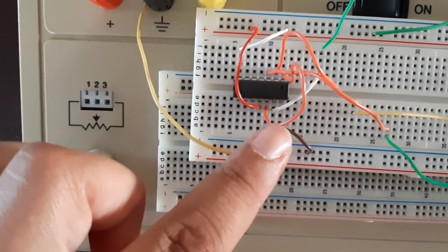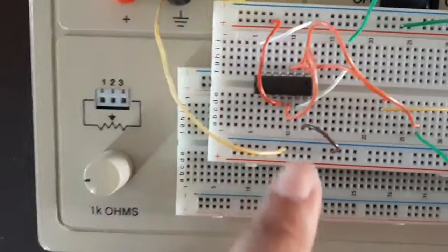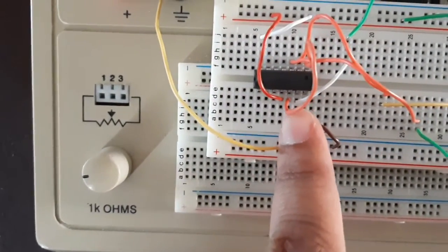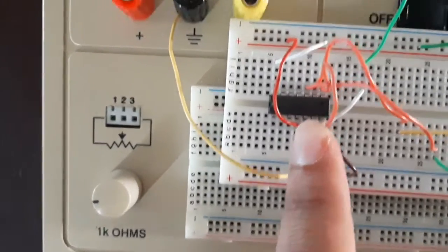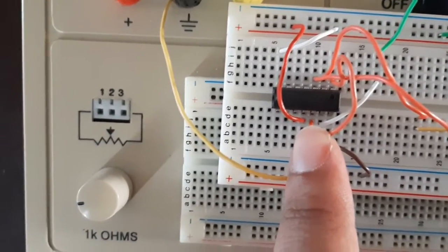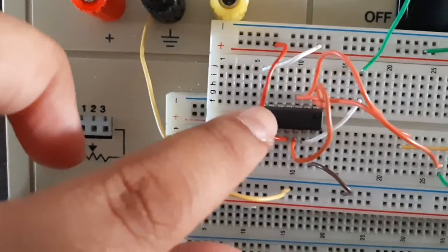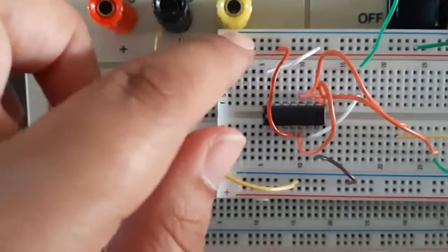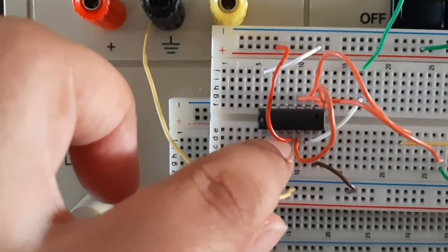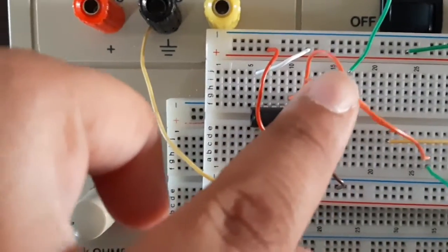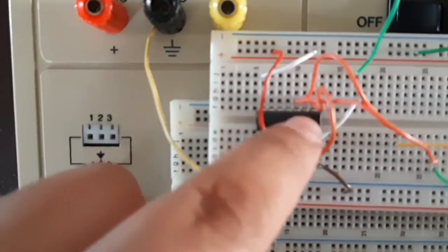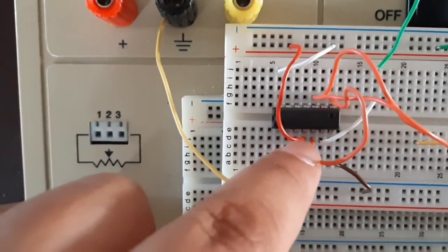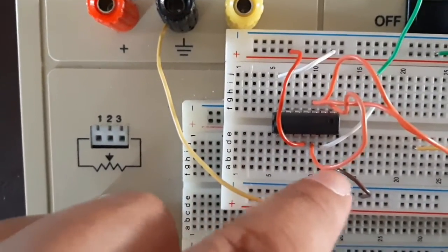Pin 8 is coming in this way and is one of the inputs. It's input B for another exclusive OR gate. And input A for that exclusive OR gate is going to be this VCC, so it's connected to the 5-volt VCC. The output of the first exclusive OR gate is now the input of the second exclusive OR gate.